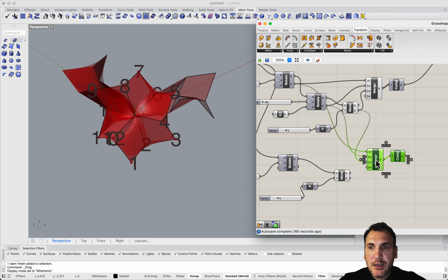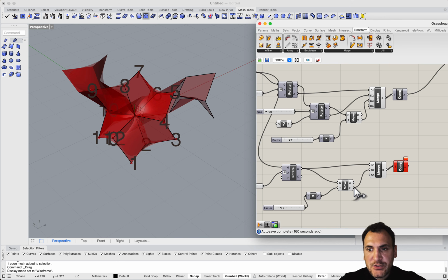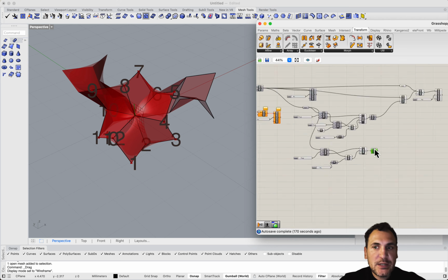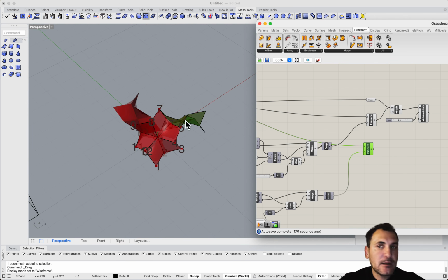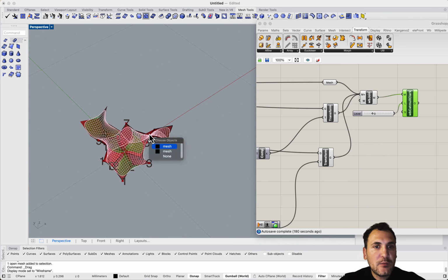So I can just make another merge of these transforms. And this needs to be x, not g. G is geometry, x is the transform. So that will make a compound transform. And if I apply it to the base geometry as a transform operation, I'll get this shape basically. So let's add this to our construction and see if it's building it the way we want.